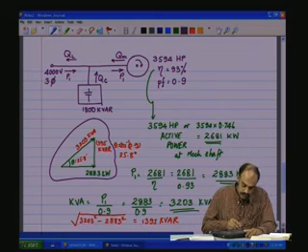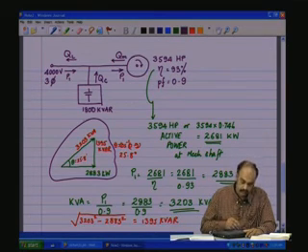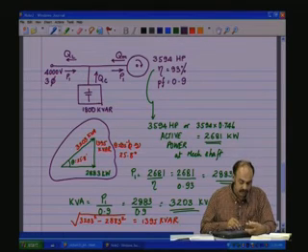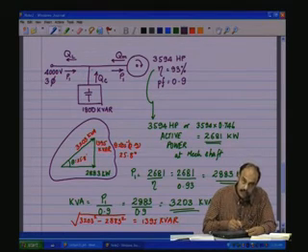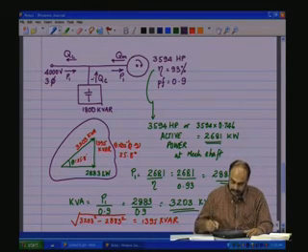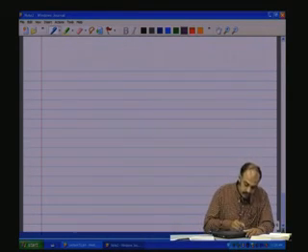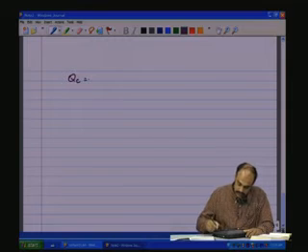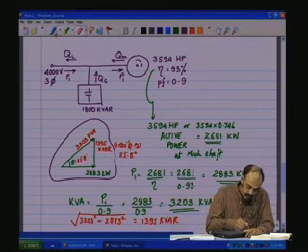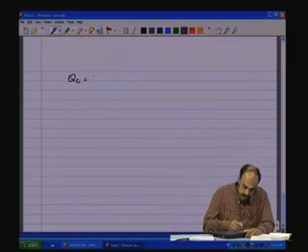You see that QC we are showing in this direction, but actually this is a passive circuit. So, if this is a 1800 kVAR reactive circuit, passive, not a generator, the QC we are now pointing in the other direction is minus. So, QC is minus 1800 kVAR.